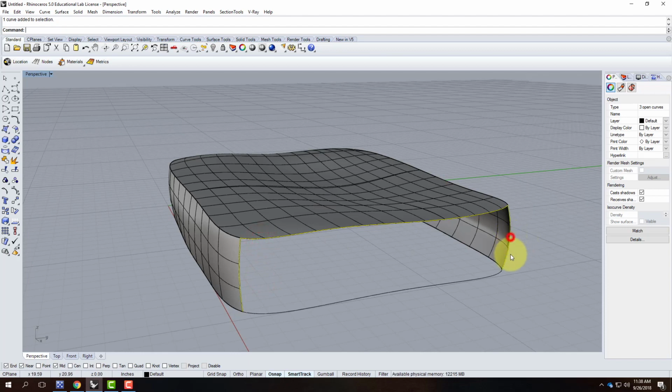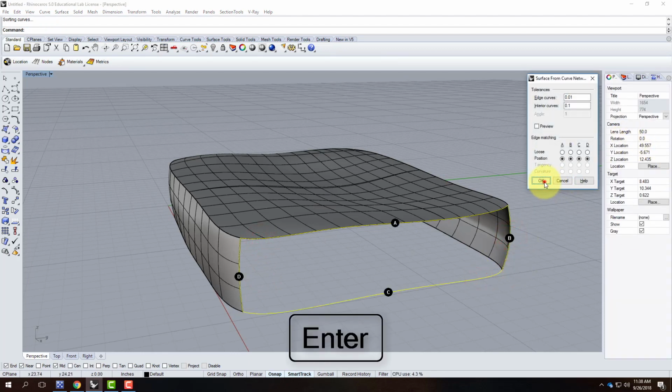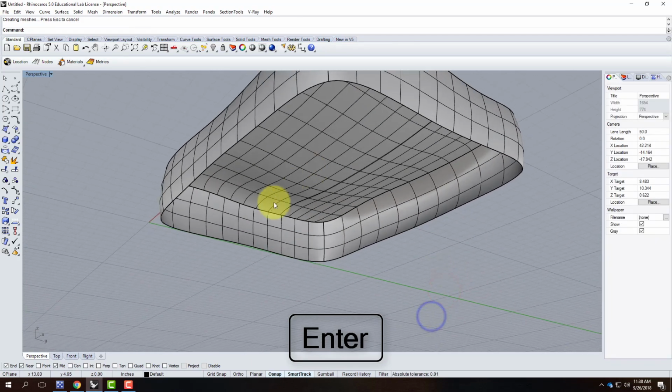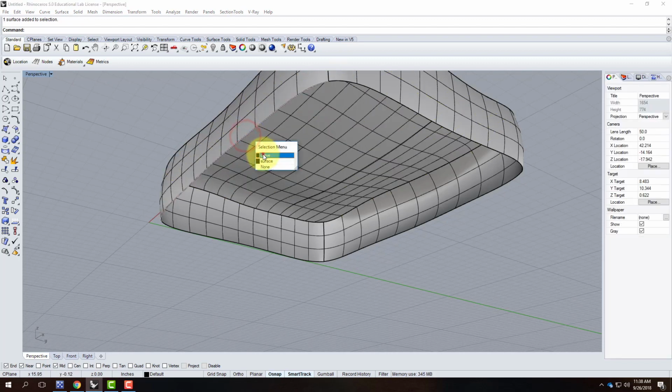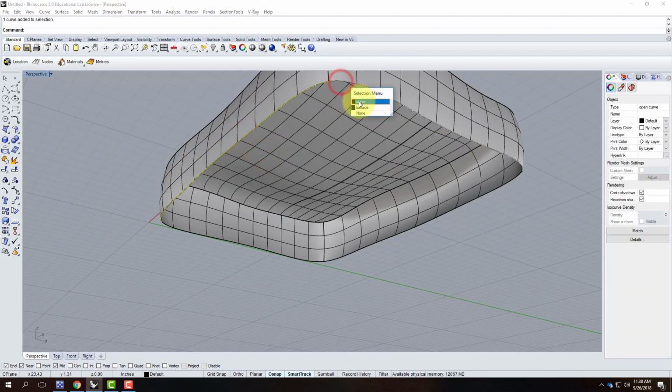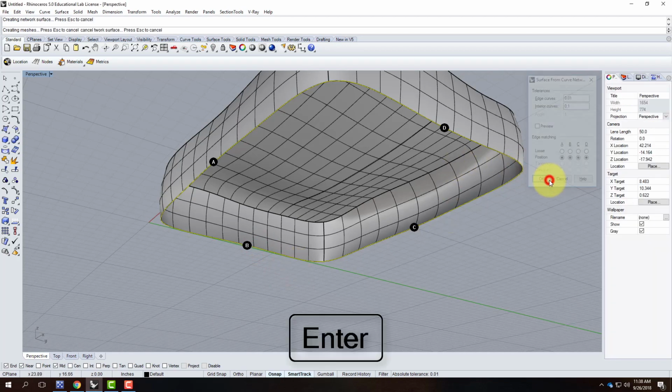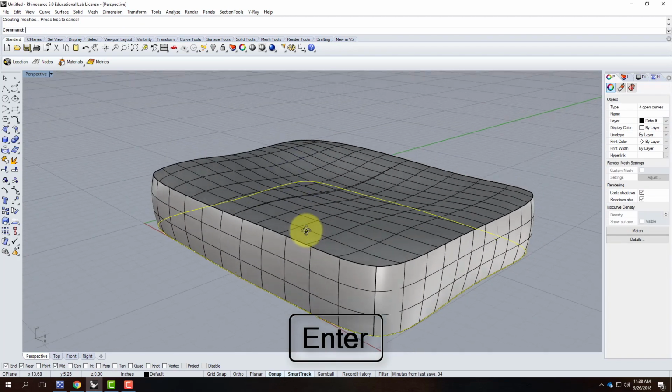And this is going to be my last piece there. I still have the bottom to do. I never built that, so we look at it from underneath. Oops. Remember, I need the curves, not the surfaces. So we'll say there, and there, and there, and there. Curve network. If you're typing it in, it's network surface.